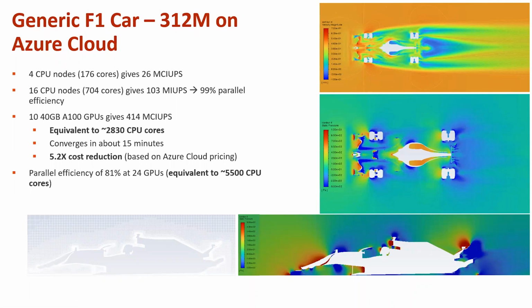So that's huge. And if you're looking at just cost saving, right? I mean, this was done on Ansys Cloud, so it's very easy to measure the cost saving that you'd be able to get by switching from CPUs to GPUs. You're able to save almost 5.2 times the cost by using GPUs. So that's, again, pretty impressive. And that is one of the main objectives in switching to the native GPU solver as opposed to using parallel CPU cores.